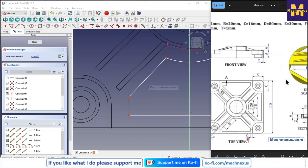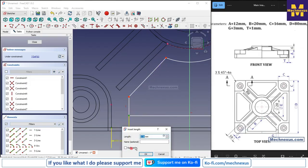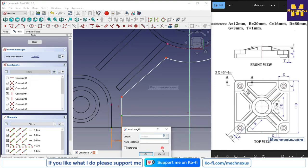So if you see here it is the value of G is given, and if you see in our parameter G is equal to 3 mm, so we will select a smart dimension, select this point, and go to the expressions, type dd dot, here G is equal to 3, so we will go here, set G, say OK.